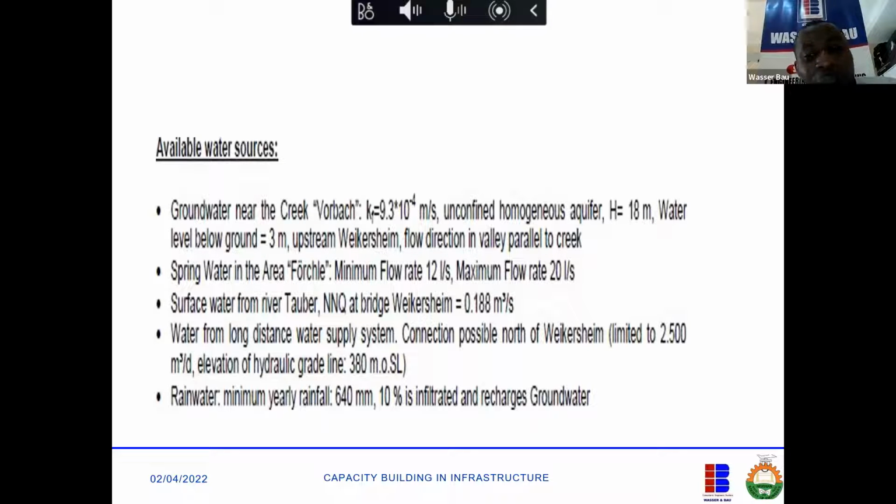And then after flowing out, you can take them through other processes like UV to treat the microorganisms. There are many of them. Chlorination using chlorides, okay, which have been banned in many countries because of the odor and fear of being carcinogenic, okay? It can cause cancer.